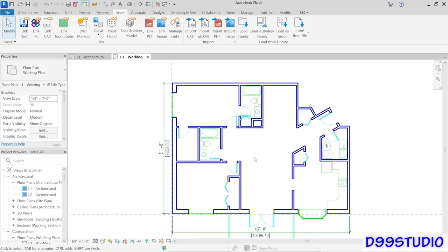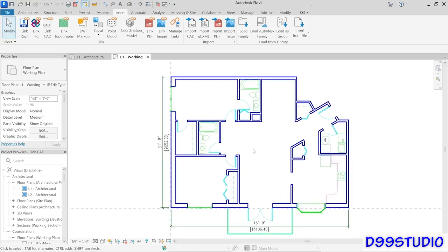So let's say that my designer worked in Autocad, and now I want to take their work and I want to start creating Revit geometry from it. Well, sadly, there's no button that's going to convert this CAD file to Revit geometry automatically. So that means I'm simply going to need to trace over this CAD file with Revit walls and doors and other elements. Okay. Now, I know at first that sounds a little daunting, but it's actually not that bad.